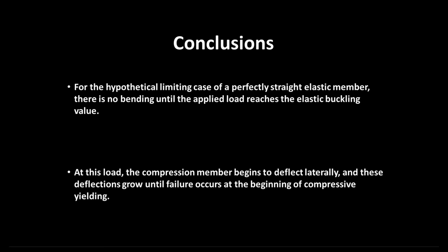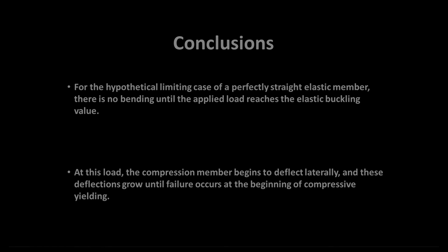From the conclusions, what did we learn? For the hypothetical limiting case of a perfectly straight elastic member, there is no bending until the applied load reaches the elastic buckling value. At this load, the compression member begins to deflect laterally, and these deflections grow until failure occurs at the beginning of compressive yielding. This action of suddenly deflecting laterally is called flexural buckling.